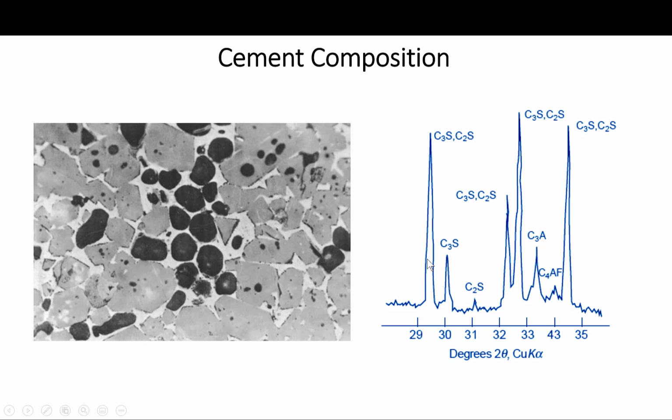Basically, there is a library you created. These diffraction peaks are converted to the D spacing. After that, the minerals are identified because each mineral has a set of unique D spacings. Typically, this is achieved by comparison of D spacing with standard reference patterns. So basically, you get a graph similar to this.